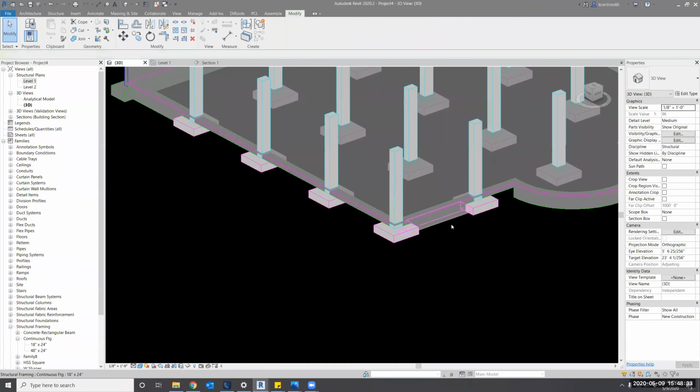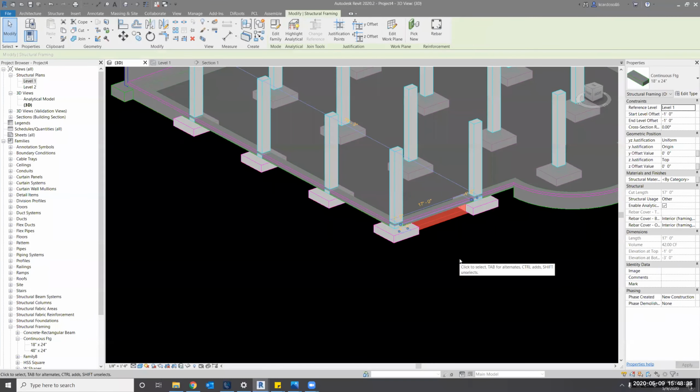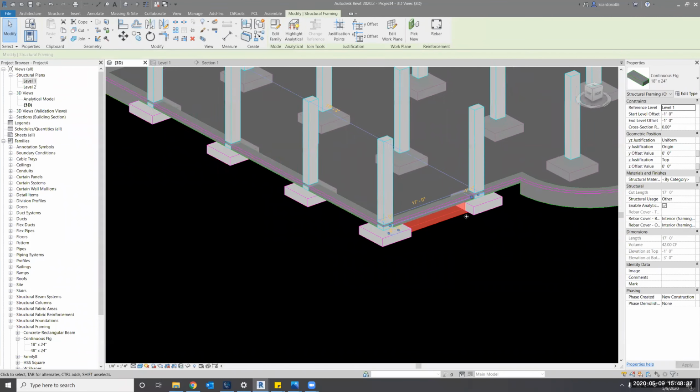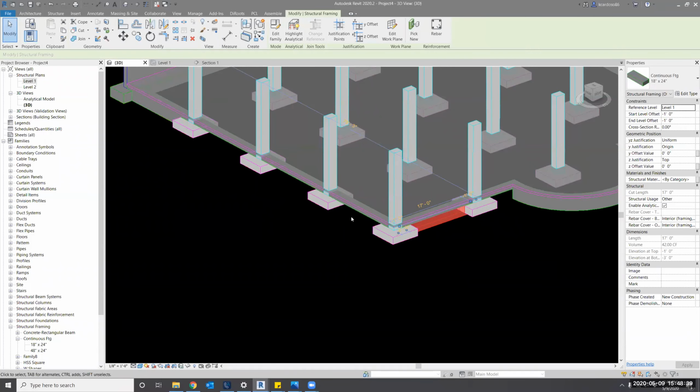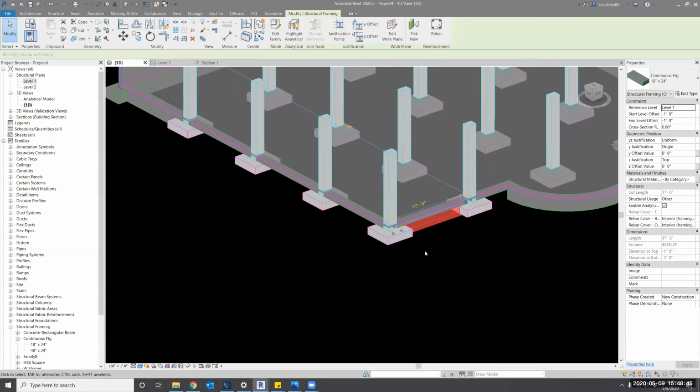But when it comes to beams, you know, we want more accurate information. So I'll use trim to extend the beam all the way to the corner, but then I'm going to split it and create separate segments, okay? Remember, we are thinking about 4 and 5D, right? And trying to implement that as a standard. That is bridging the gap between design and construction and making this information truly usable.